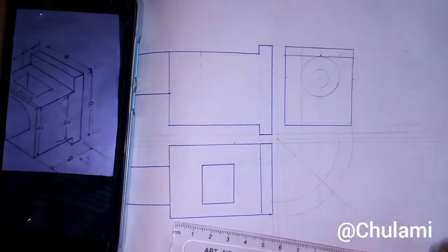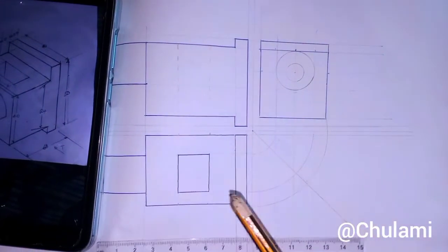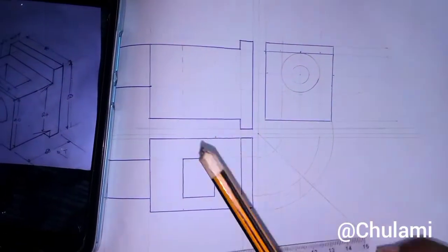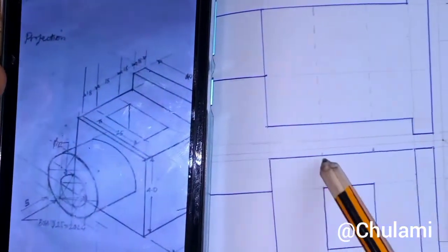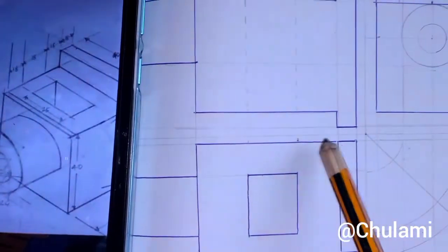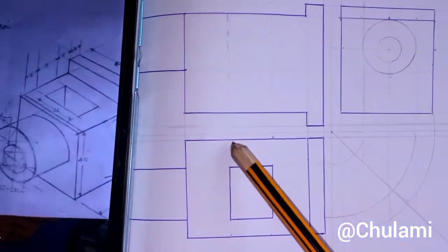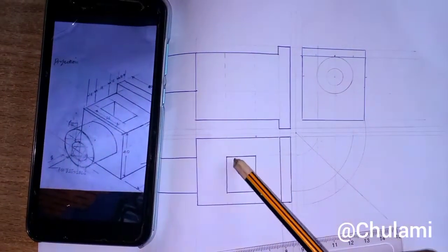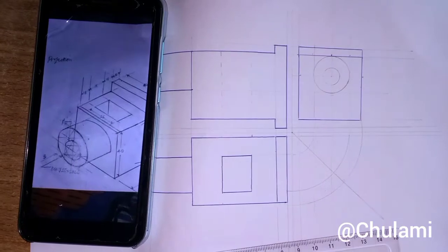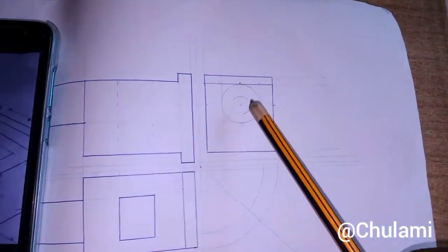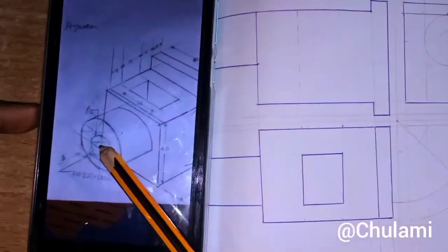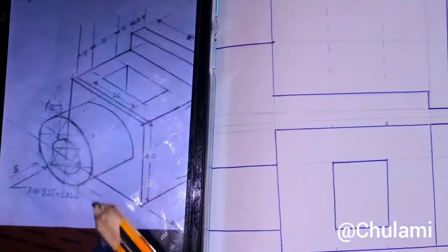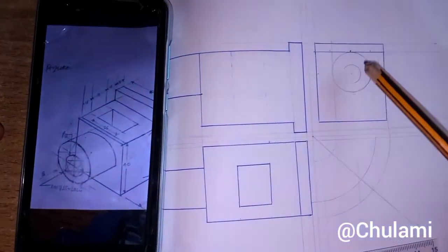So okay, now I drew the circle. If you watch, I also use this same line to guide me to draw the circle. We had the dimension of our circle from here to here, 18, 18, and 18. So with it, I just drew it and I followed this sequence. Then they also give us the radius of this smaller circle inside, which is 0.5 cm. So with 0.5 cm, I drew this circle with my compass.